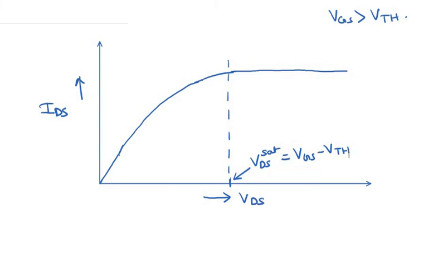And we also know that if we increase this value of VGS, then the conductivity of the channel is also going to increase, because increasing the value of VGS basically induces more electrons in the inversion layer, or increases the average density of electrons in the inversion layer. Okay, so this is, let us say, for VGS2.